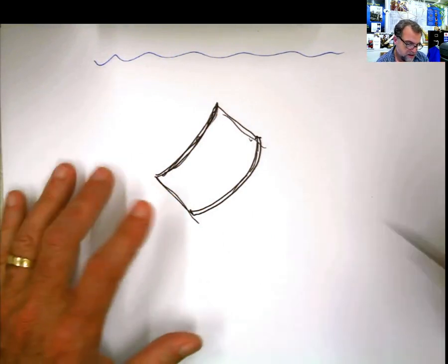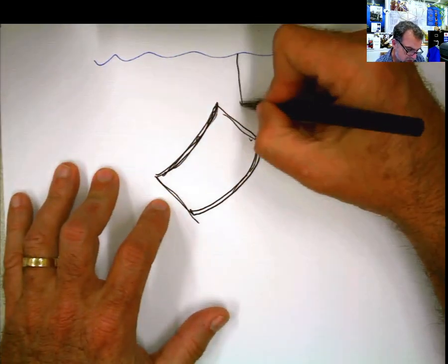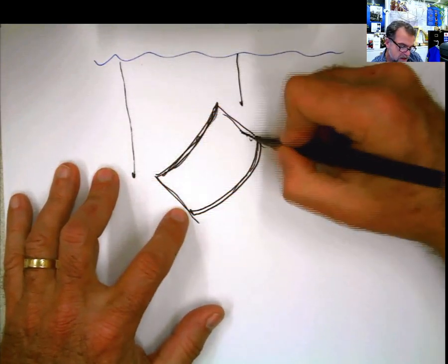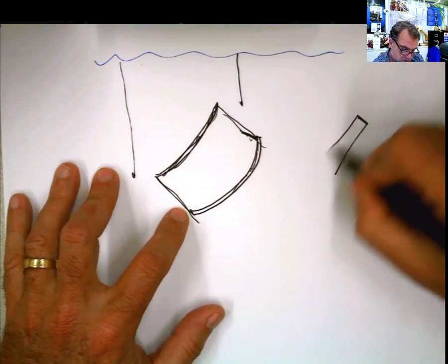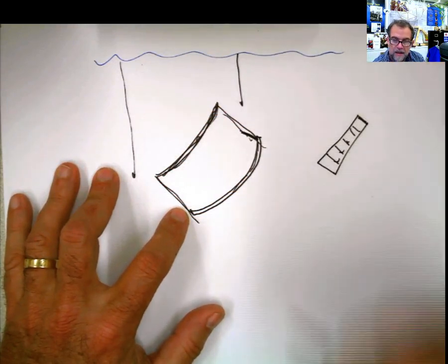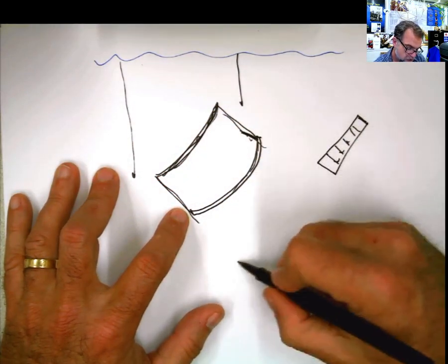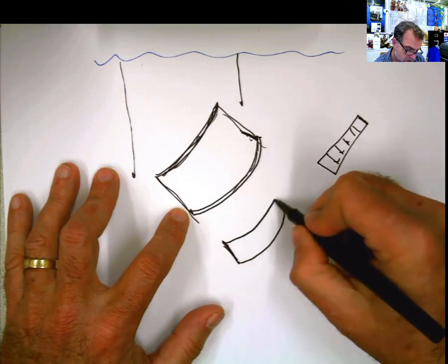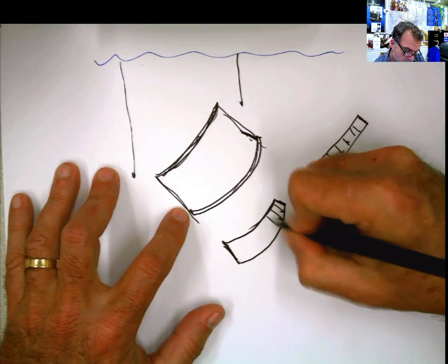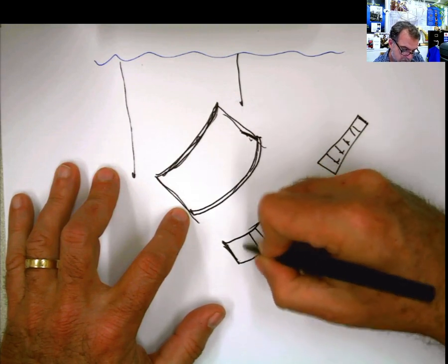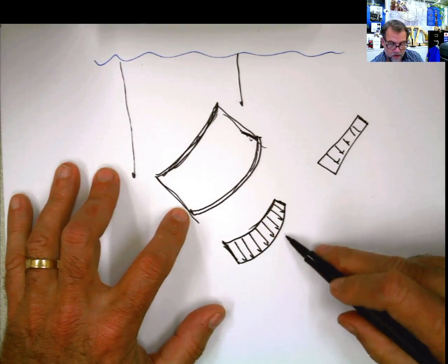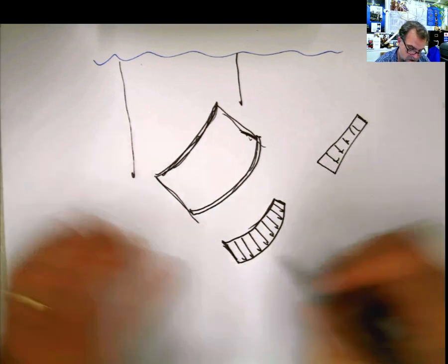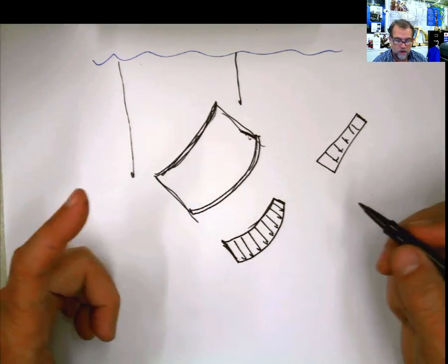The principle is the same. You calculate this depth here and this depth here, at the top and at the bottom, and then what happens is that instead of being a flat plate like that, now we have a curved plate. But the principle is the same. Now we have a curved load, which is acting always perpendicular to that plate, something like that. Now instead of doing this, because you can do this by integration, by integrals, and calculate this same thing, the same way that you calculate the centroid, and the same way that you calculate the area.